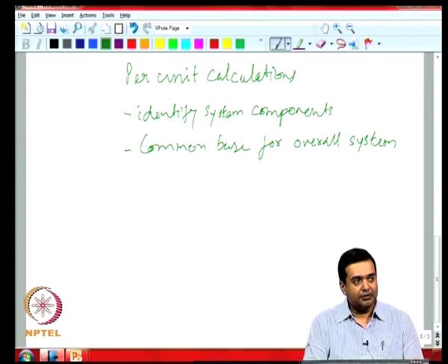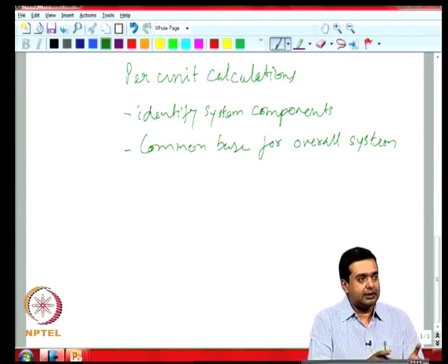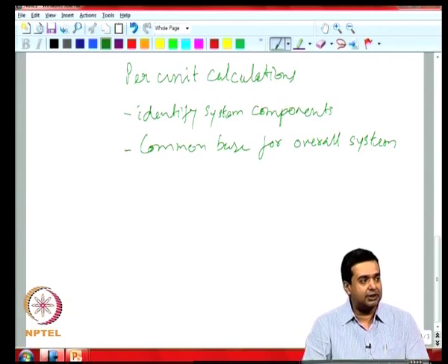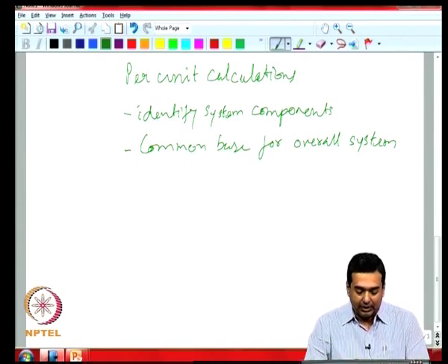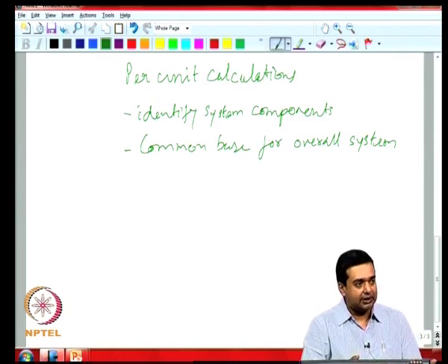And you identify the location of interest to you. It might be your consumption point where you are doing your calculation, or some distribution transformer where you are doing your calculation. Depending on the region where you are trying to do your engineering analysis, you bring it to the common base associated typically with that particular point. Then you transform all the values to this common base corresponding to this common point, and essentially when you do that with transformers, your transformers become transparent on a per unitized basis.